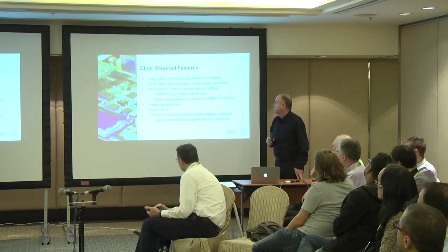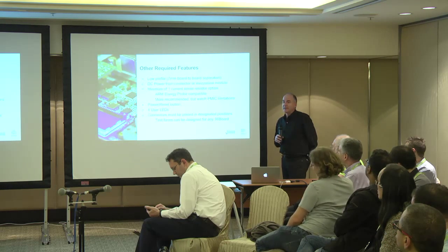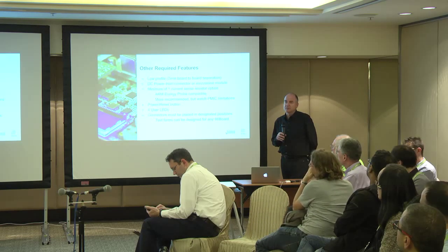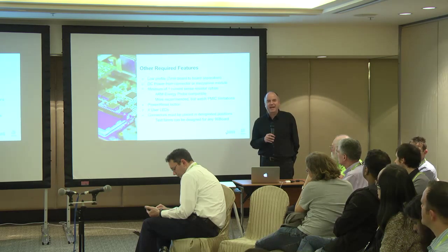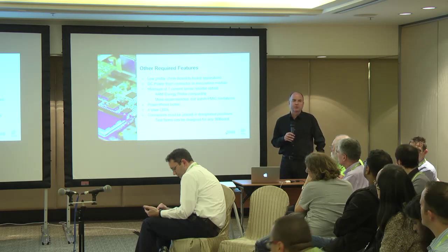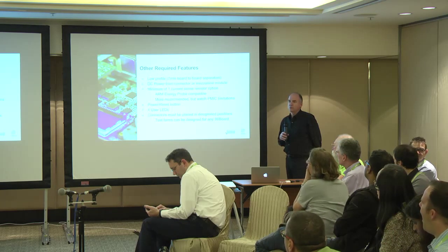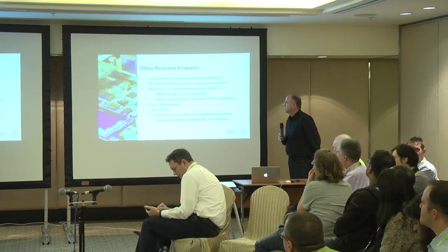For our own purposes in the power management group, we wanted to see current sense resistors to do power management measurements. The more the better. You do have to watch out for PMIC limitations. Most of the PMICs are very sensitive to putting any additional voltage drop in their output lines. So how much you can do without a lot of cost depends on your PMIC implementation.